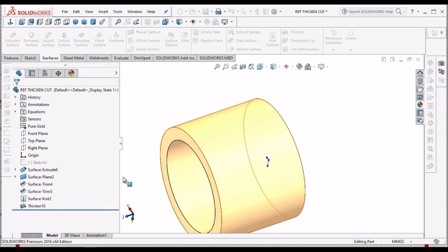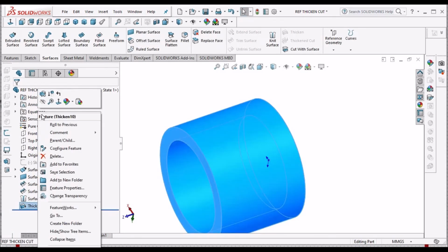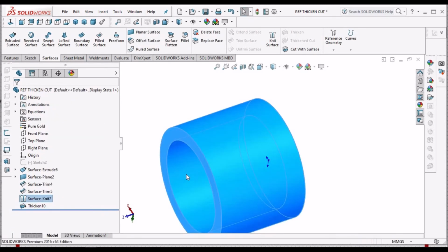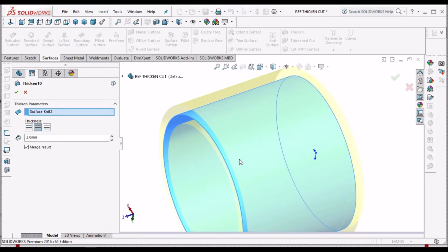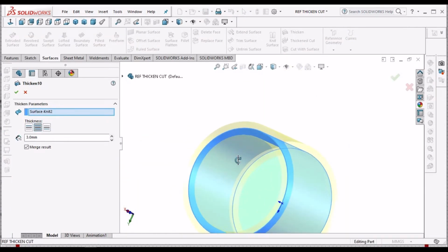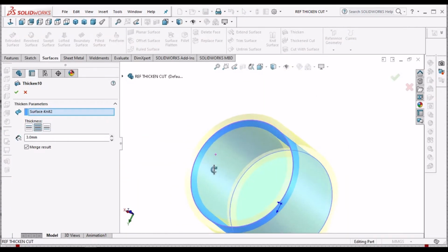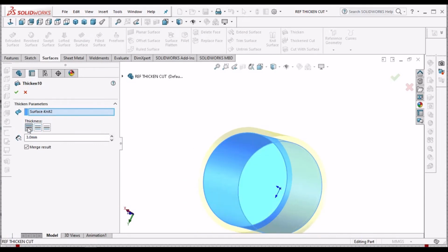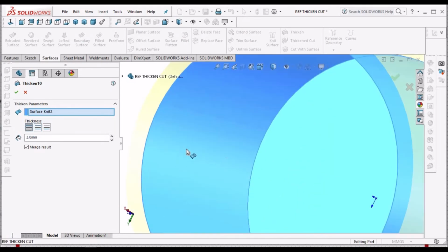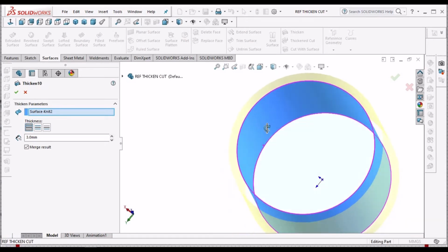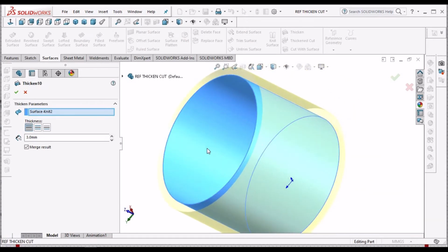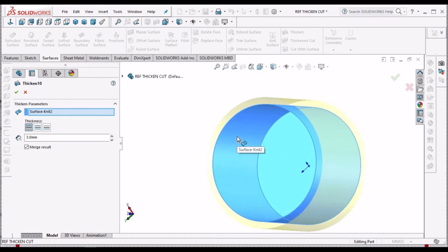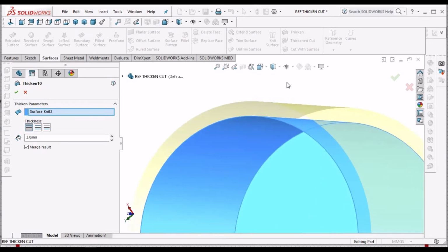Whenever we add thickness to any surface, we have to consider which one is the reference, inner surface or outer surface. For example, if it is a bottle cap, the inner one is the reference surface for dimensioning because it's going to fit on the bottle top. So we will always be adding material from outside.